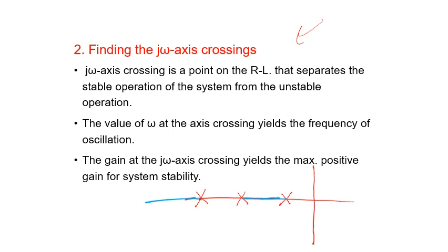According to behavior at infinity, this is going to go toward infinity in this direction, and this one is going to go with this direction and this direction. They are going to meet at a certain point. We call that point breakaway, if you remember. So we calculated it, and then they are going to travel at angles of 60 and minus 60, this way toward infinity, and the other the same thing.